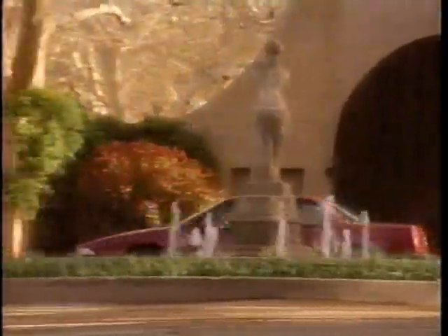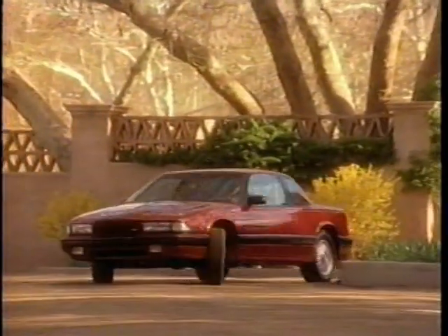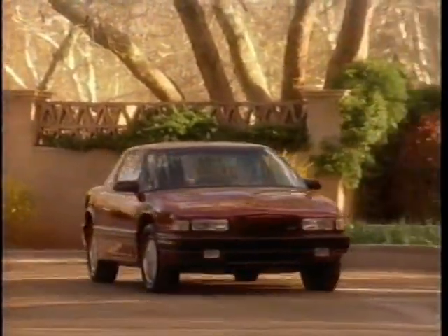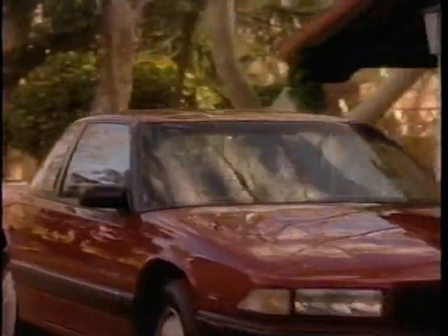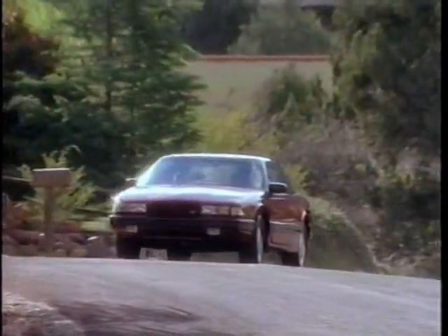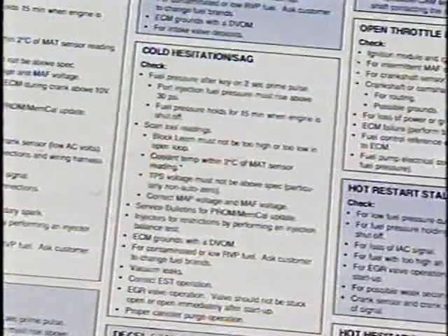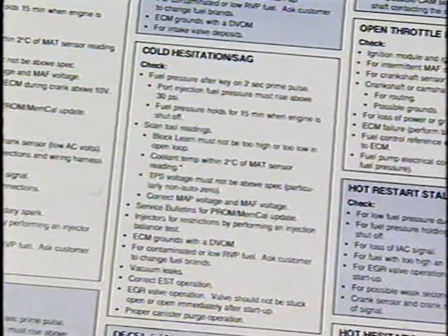Some drivers of vehicles with a 2.8-liter or 3.1-liter engine have complained of an occasional engine stall, sag, hesitation when accelerating, or a chuggle at steady throttle. While you know there are lots of components that can cause these problems on the 2.8-liter or 3.1-liter engines, let's look at the EGR system.